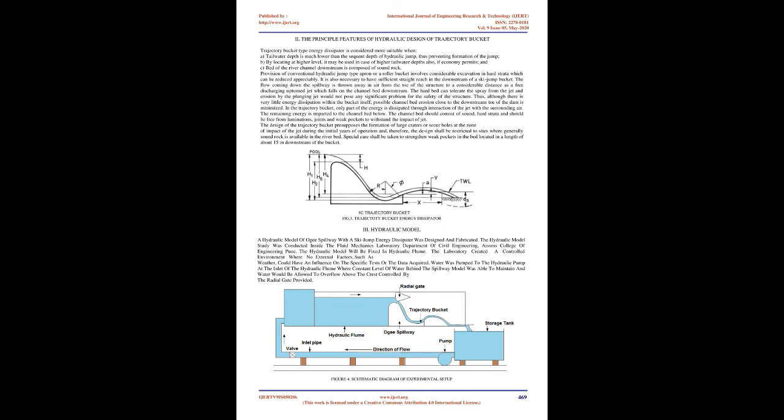Special care shall be taken to strengthen weak pockets in the bed located in a length of about 15 m downstream of the bucket. Fig. 3 Trajectory bucket energy dissipator.